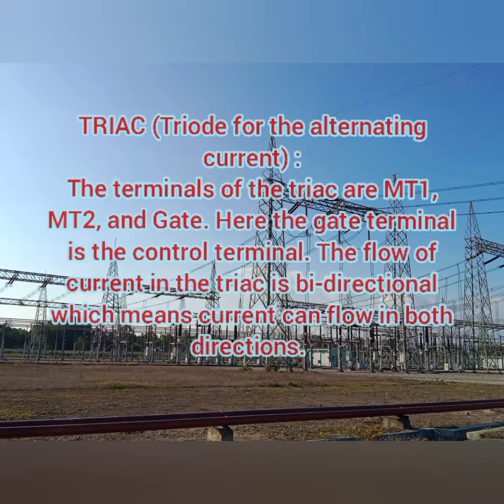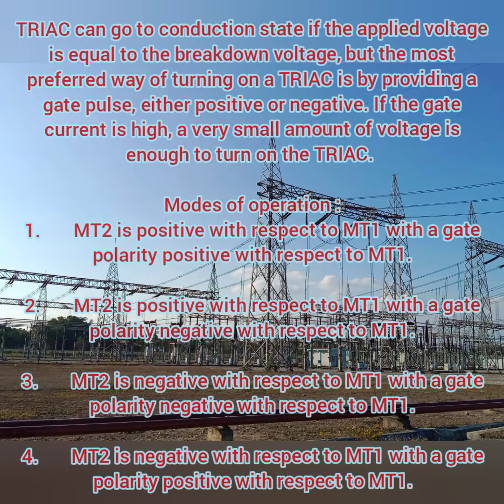Next, coming to the TRIAC, triode for alternating current. It is the same as a DIAC, additionally we have a gate terminal. In this way, controlled triggering can take place in both directions, which means for forward and reverse conditions this controlled triggering can be made. The TRIAC can go into conduction state if the applied voltage is equal to the breakover voltage, but the most preferred way of turning on a TRIAC is providing a gate pulse, either a positive or negative pulse.